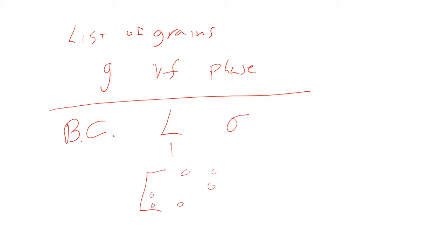So we force the off-diagonal terms to be 0. And since it's compression, I give it -1 here. And then these are undefined, right? I don't enforce my axial strain. All I do is I say, overall, I'm going to be compressing at this given rate, right? And then the terms that are not specified in terms of displacement, I have to specify them in terms of stress.